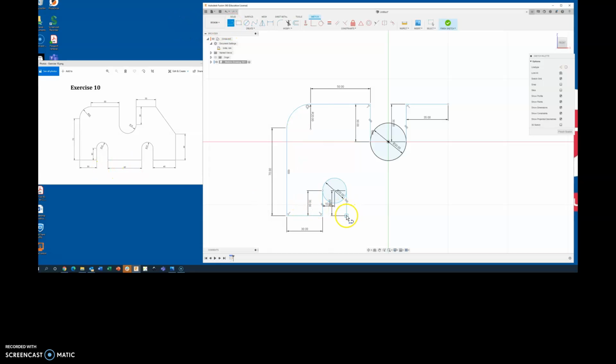Keep on keeping on. I'm going to go over to the right 60 millimeters. I'm going to come up 20. 20. I'm going to make my little 10 millimeter line again. I'm going to do my circle. And then I'm going to delete out my little line. Start at the center, dotted line over to the edge, got my X, click, come down 20.